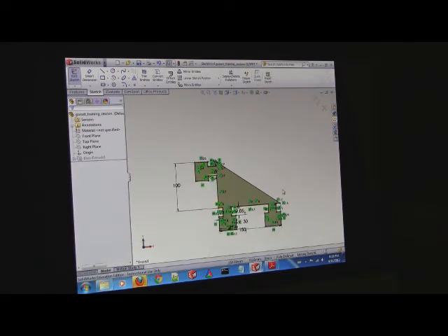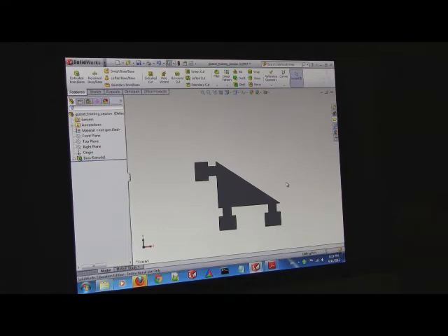Okay, does everybody have a third wedge? Once you have your third wedge, I want you to re-extrude it so we can make sure it's working. Often if you're doing a complicated sketch, it's good, once you've done a little section of the sketch, to extrude it to make sure there are no issues, and then save it and go back in, because trying to debug what relationship went wrong out of 1,000 little clicks is really hard.